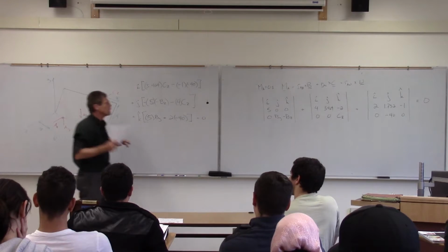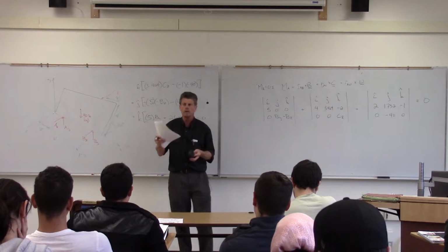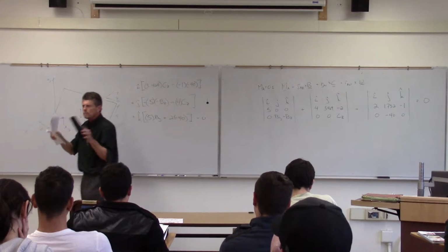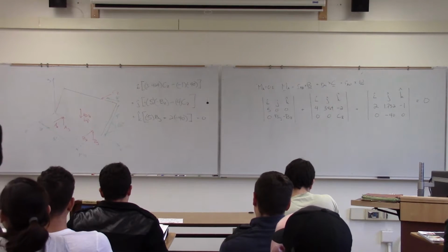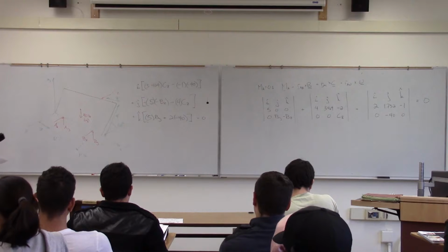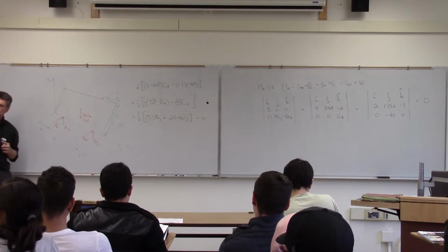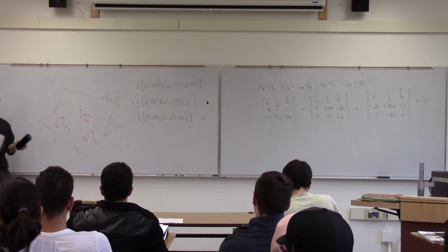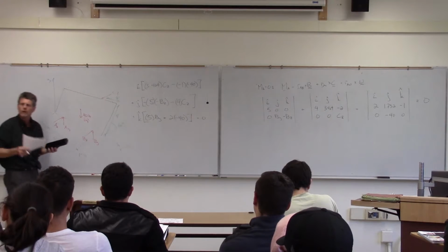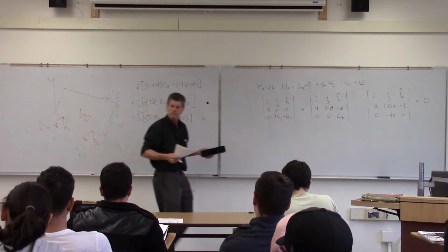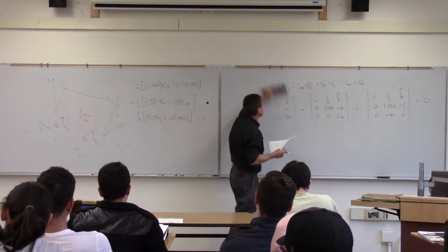What we'll find, and it brings up a good point, is that oftentimes the first thing we usually want to do is a moment equation. And we want to take a moment equation where we can eliminate some of those unknowns. Once we do that, though, we can maybe just do sum of forces for the next couple of equations. So let's finish up the problem.